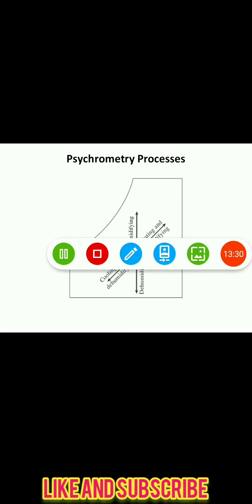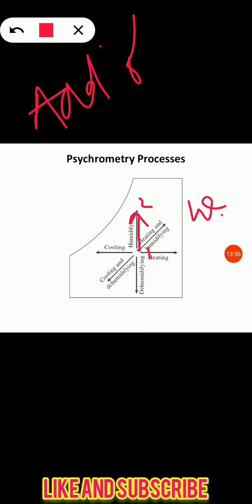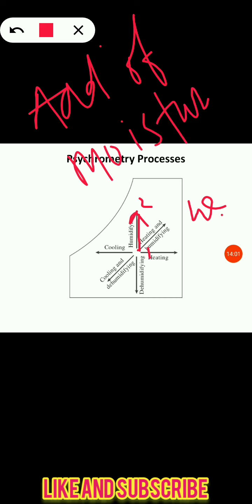Now next is the psychrometric process, the humidification. In the humidification process, we increase the specific humidity of the air. Suppose this is the process 1 to 2. So here the process is known as the humidification process. In the humidification process, we generally increase the humidity of air. Humidity of air may be increased by the addition of moisture. So the arrangement will be done in such a way that moisture will be added in the air, so that the humidified air will be supplied to the room.